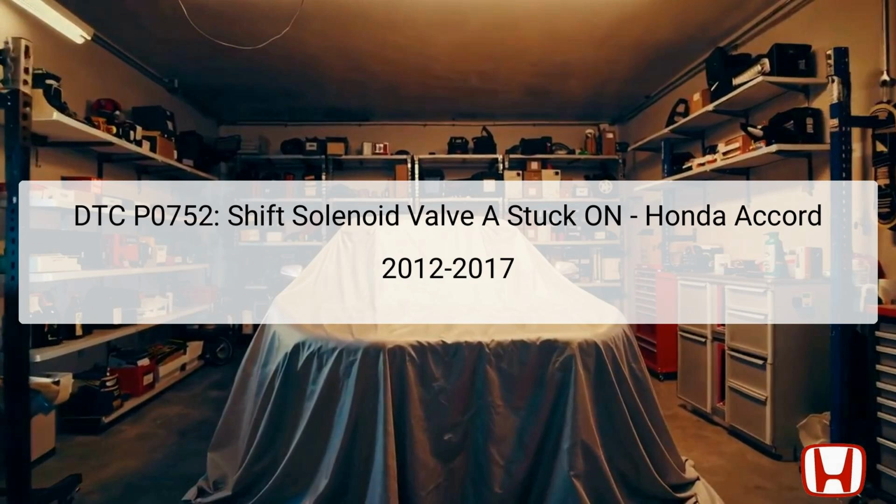The Powertrain Control Module, PCM, sends signals to this valve, directing it to regulate the clutch pressure according to the vehicle's gear shift schedule. When this solenoid malfunctions, the PCM detects an improper gear ratio during shifts and logs the DTC, affecting overall vehicle performance and drivability.